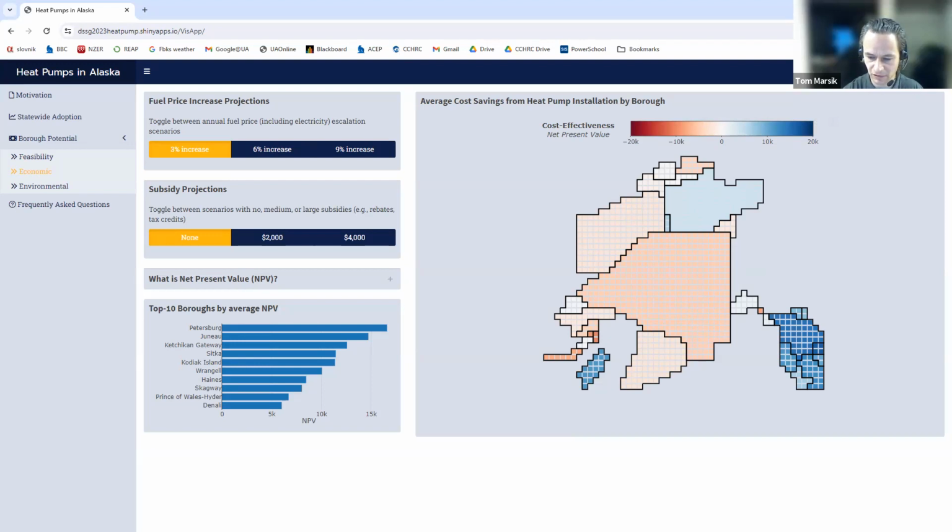Okay, we currently have an old boiler with baseboard heaters. Any way to tie in the two systems? So that's a great question. When you have a boiler, a kind of initial idea for most people is, can I just replace it with an air-to-water heat pump? And the answer is it's not easy. So for one, you would lose your backup heat source if you just replace it, and you do need a backup heat source in places like Fairbanks.